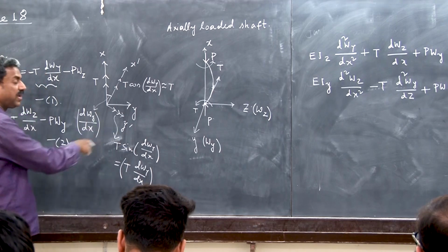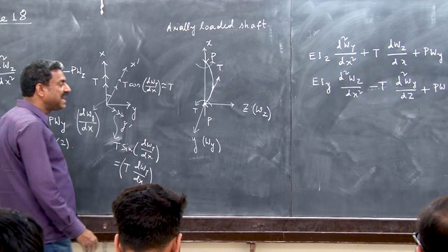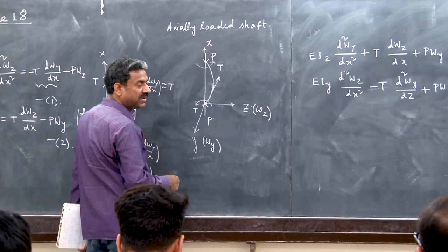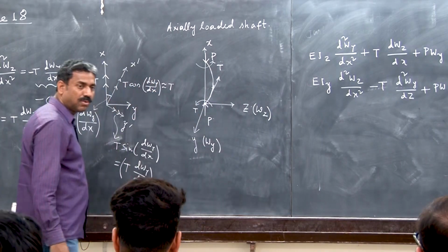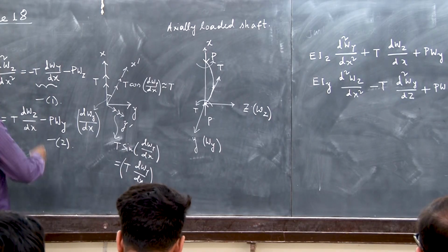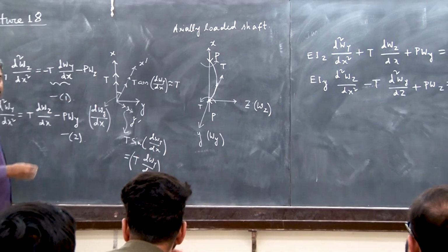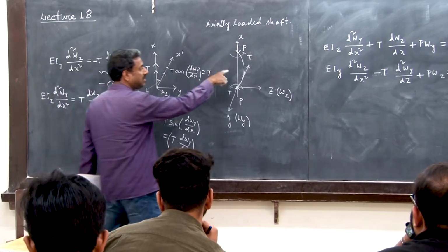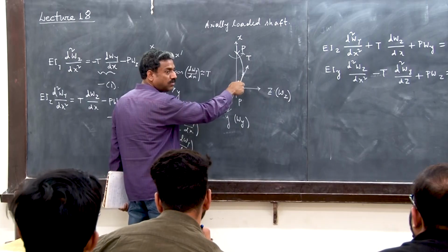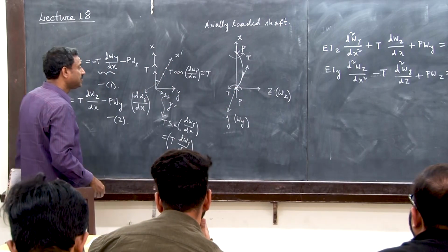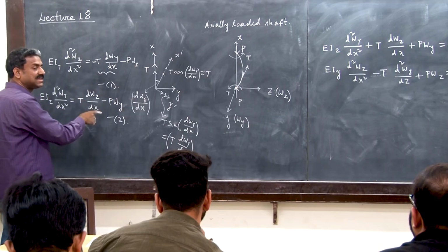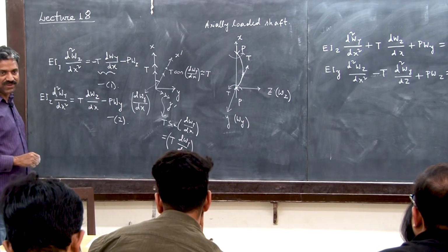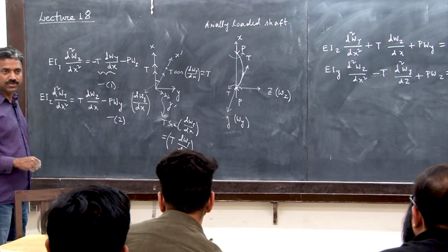So of the two bending moment components we have, we can clearly understand that one will be along z and one along y, right? That we have considered. Then there will be another component that comes because of the axial force. Because of this deflection, it will also contribute a moment, P into W, right? So in both cases, the total bending moment we take and write down is nothing but the bending equation, M is equal to EI d2W/dx2, right?